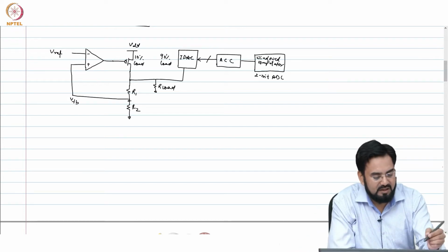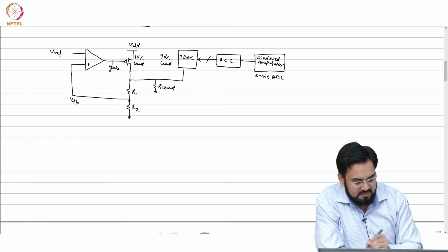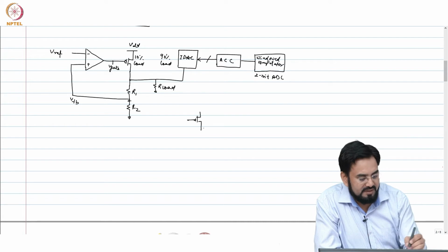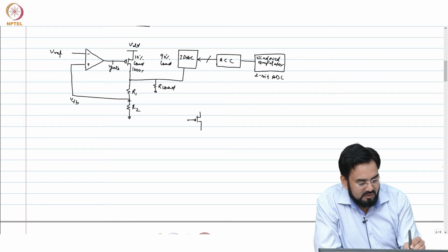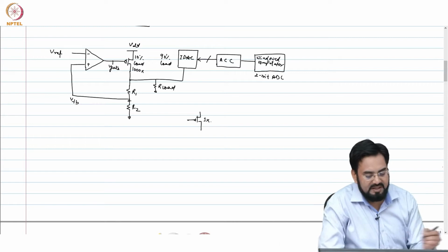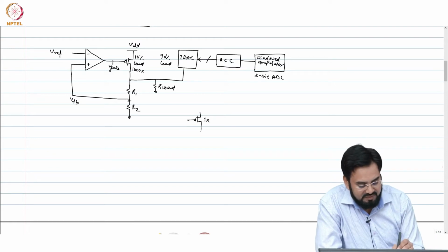So if I want to sense the current, we already talked about that. So if this is your V gate, all you need to do, just take this. Okay, so if this is, let's say, 1000x, you make it 1x device. So at 1 milliamp it will carry 1 microamp only. So which means you have to compare this with 1 microamp reference current.